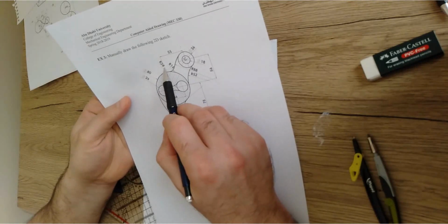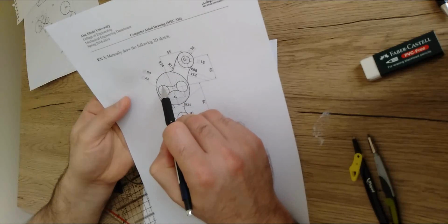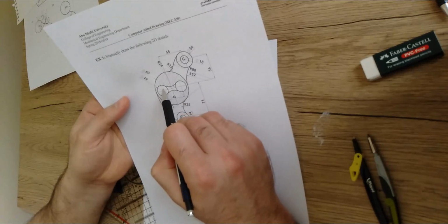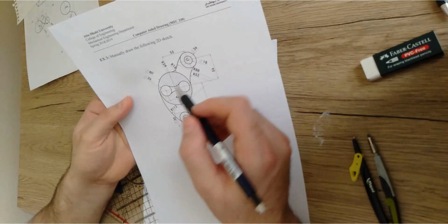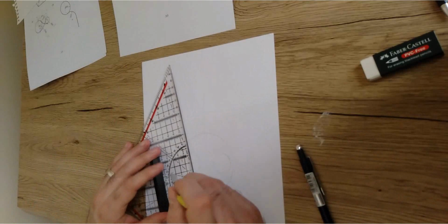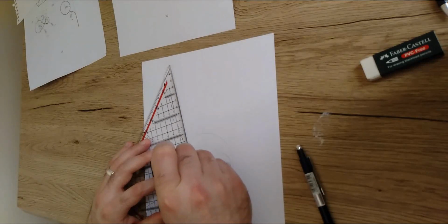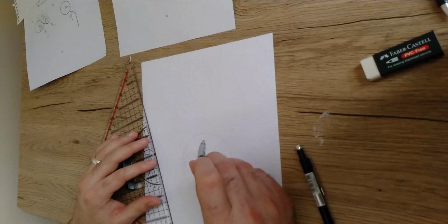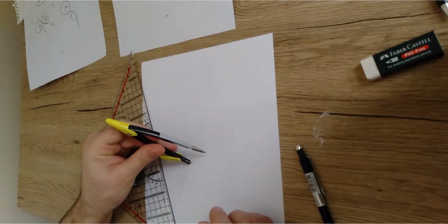Then I'm going to do the same. If you try to move from the center of this curve to the center of this circle, we're going to go over the tangent point. So we're going to add as well 13 plus 24. So in total it gives 37 as well. So from the two centers, I should open the canvas by 37 millimeter. Then I'm going to draw a curve from this center and another curve from this center.